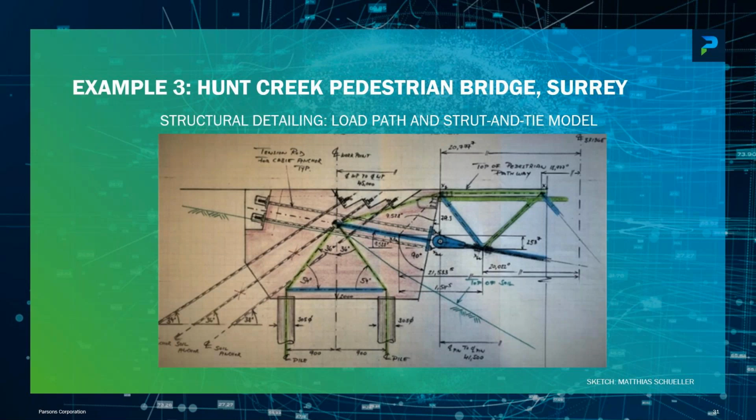Now, from a construction perspective, you don't want to see much movement in this table. So you need to stress these solid anchors first, but when you stress them, against what are you stressing? Because then you would pull that table back. So we didn't need this center soil anchor, so we put a micropile in instead, and that micropile acts as a pile and resists these soil anchor forces. And then when we start loading these suspension cables, we just take the load from the micropile away, and then you don't see much movement. That was the idea.